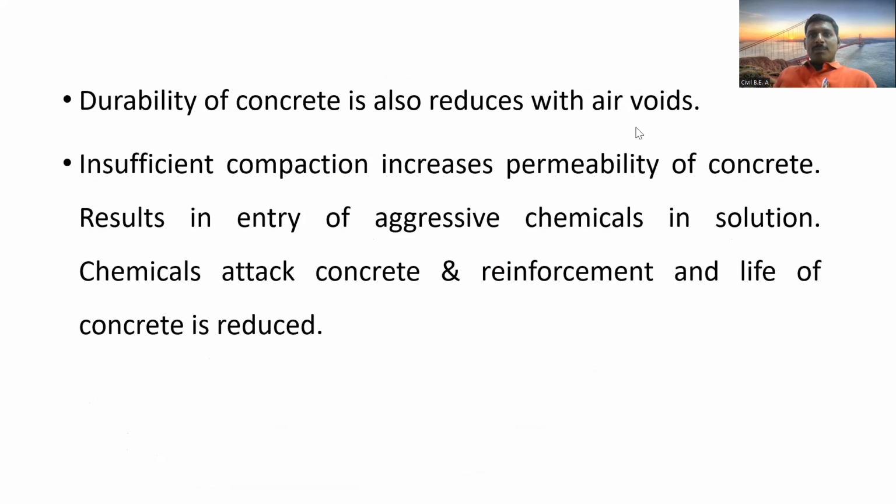Also, compaction is required because the durability of concrete is reduced if air voids are there. How will durability decrease? Because of air voids, the internal air will attack the steel and the concrete, and there may be a chance of weak regions and also corrosion. The density of concrete will be reduced, so the durability is also reduced.